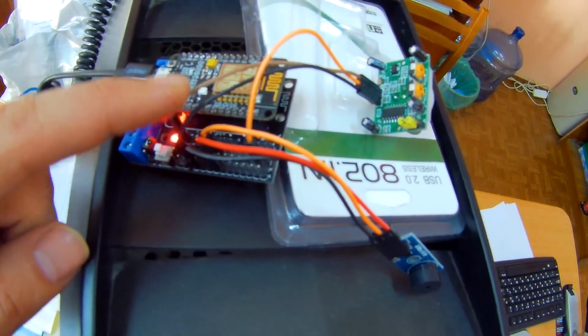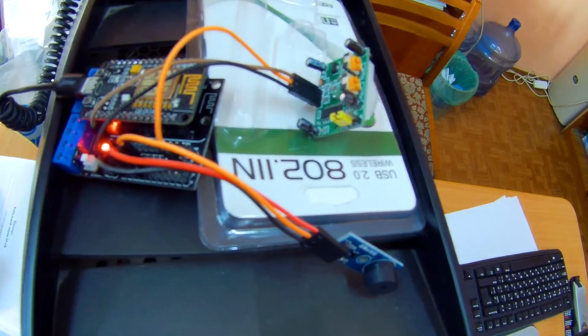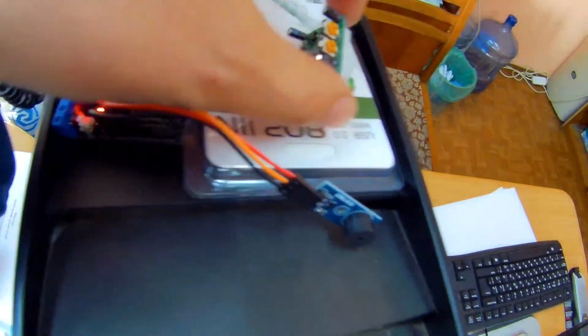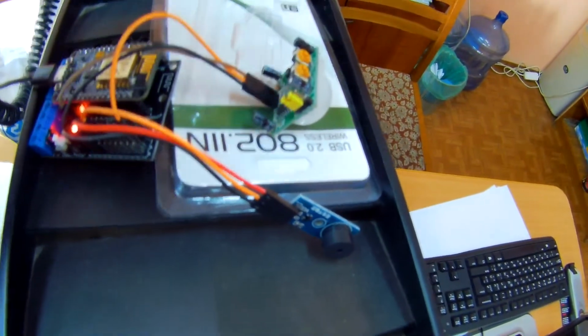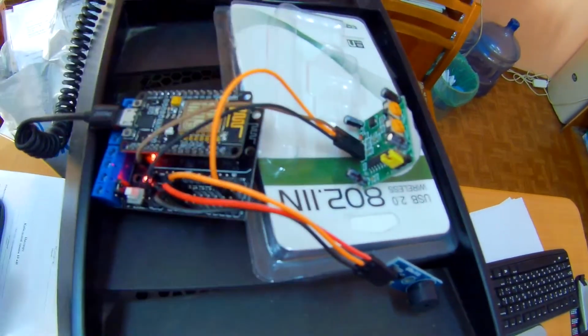Same voltage. Otherwise it doesn't work, because on output it would have 2.6 volts and not 3.3. But if power is 5 volts, output will be 3.3 volts, and you don't need any additional stuff to mess with.